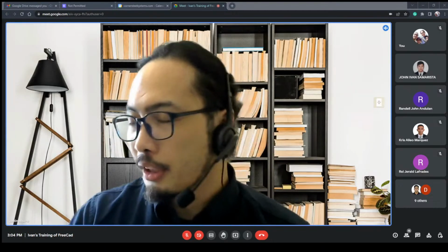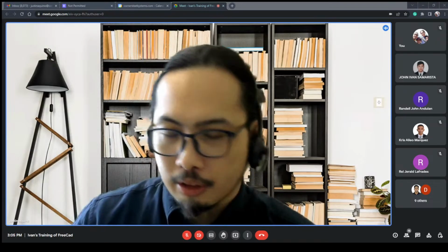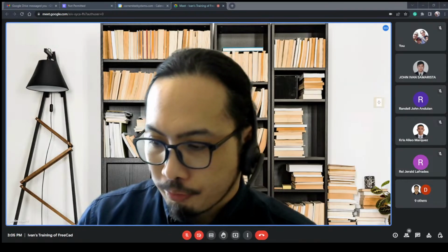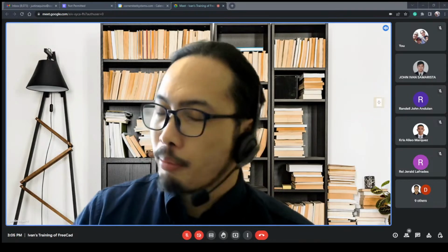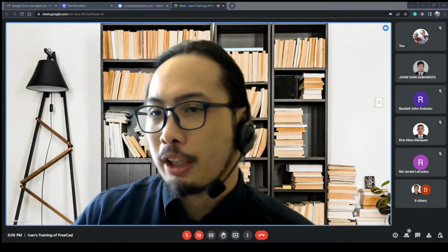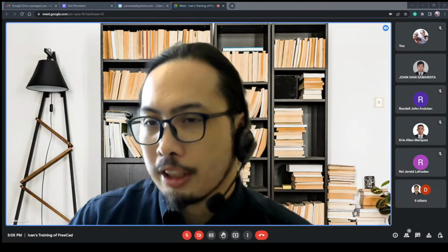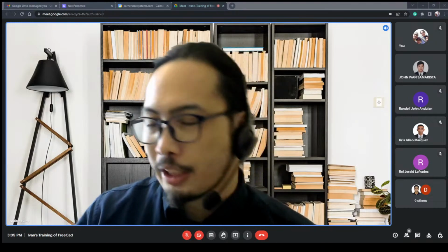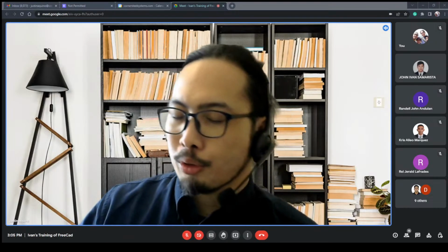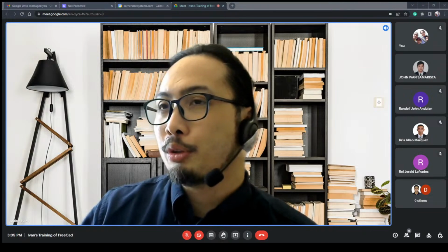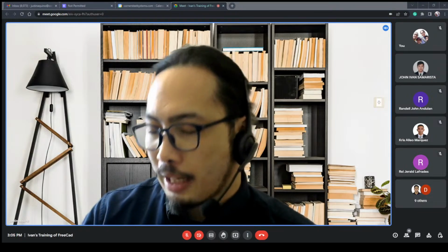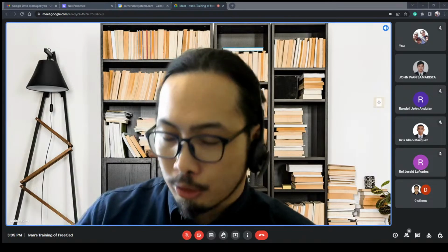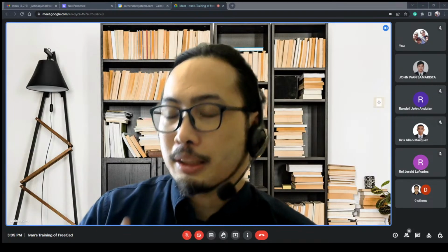And of course, I put the dimensions so that it's visible, not only in the spreadsheet. So the purpose of that is that I don't have to manually, I want a new table of certain dimensions, I just input in the spreadsheet what I want. I don't have to go into Sketcher, I don't have to go to thickness, I don't have to go to padding, I don't have to go to the other controls. Everything is in the spreadsheet.